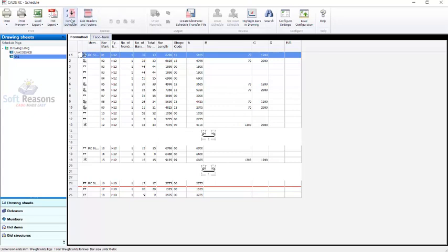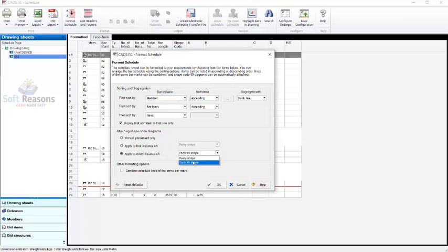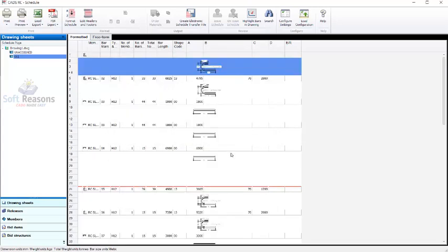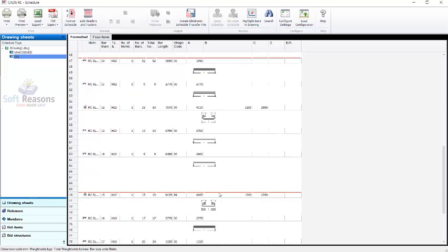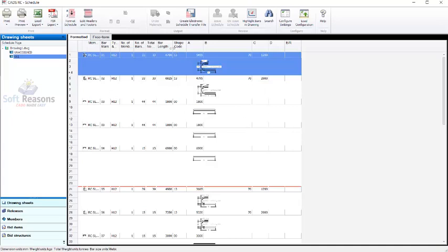Okay, so we can also get to format, close this, and then you can use every shape. Each shape, use every shape options and then click on OK. So you now see all the shapes of the bars that we have in that slab detail successfully, just like this. So you can proceed to print this in Excel or plot it to PDF. If I want to plot it to PDF, you can see bar schedule report, you can see weight report. So you can get the bar schedule report and the weight summary report successfully.